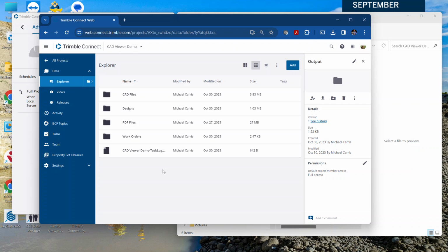So it's really advantageous to have a Connect account and connect your controller to the web. Now you can send data back and forth. It's backed up. You can use the CAD viewer to create your as-built and your data prep, and everything is there for you. So again, hopefully this gives you an idea how you can use Connect in concert with Trimble SiteWorks and create a workflow to easily take your CAD data, create a data prep file, send it out to the controller, do some collection measurements, as-built and whatever, and bring it back.